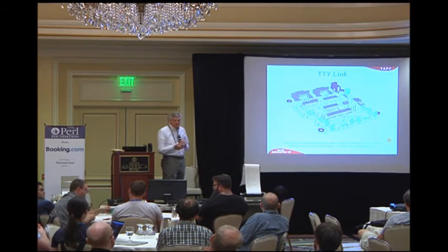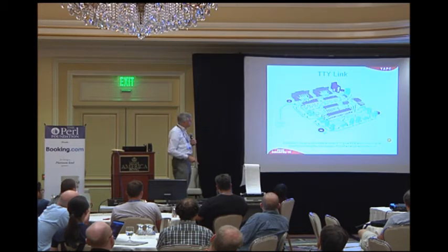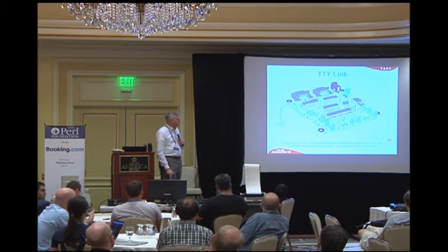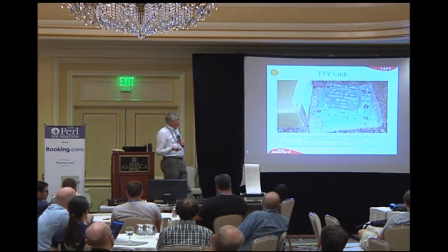One of the nice things about the software is it lets you see everything in 3D, and you can rotate this board in 3D. And when I did this, I actually found an error. I noticed that there was a little gap between those two wires. And sure enough, the little via point, it's called, was not there, so I would have had to open a break in my circuit. So that was nice to find that.